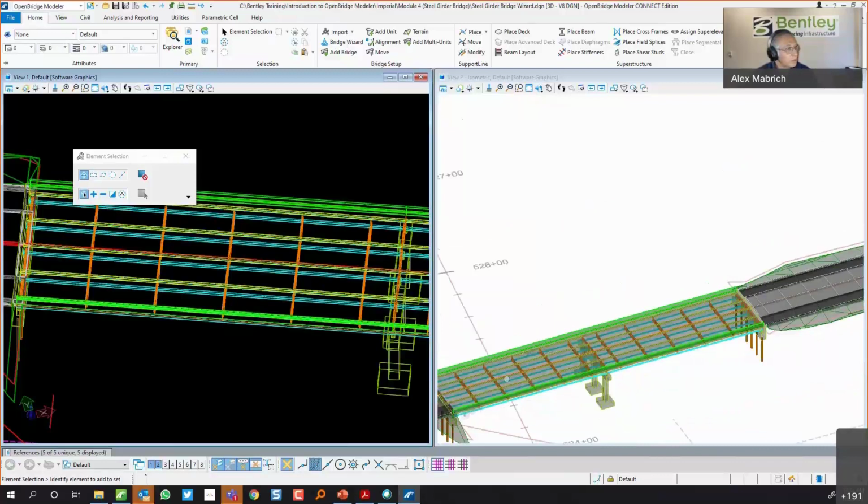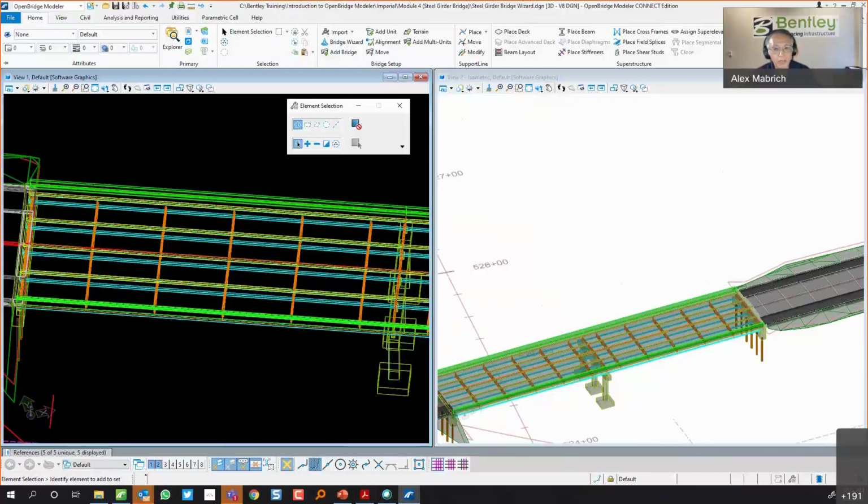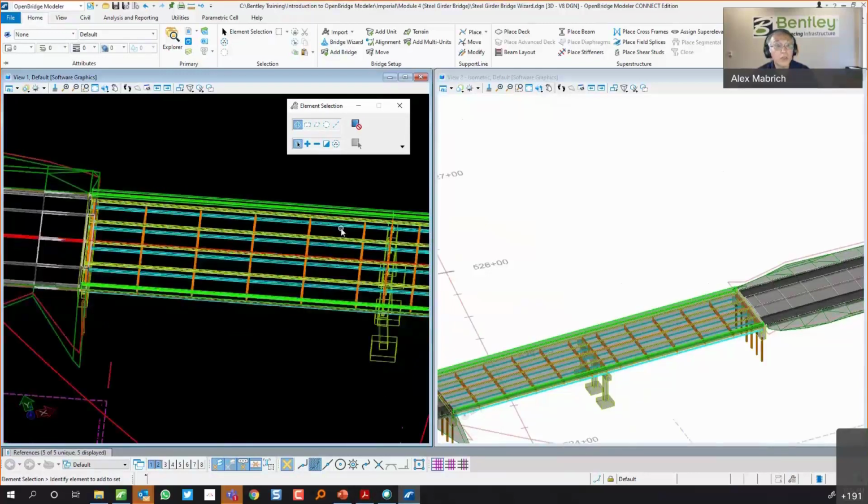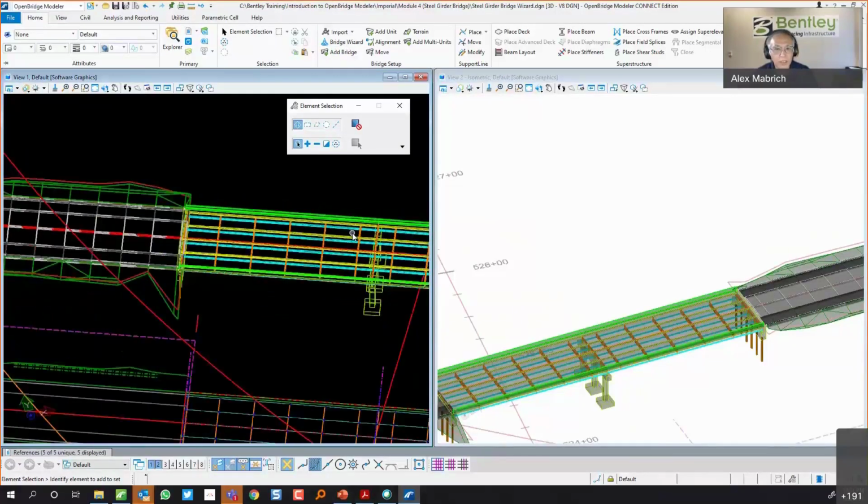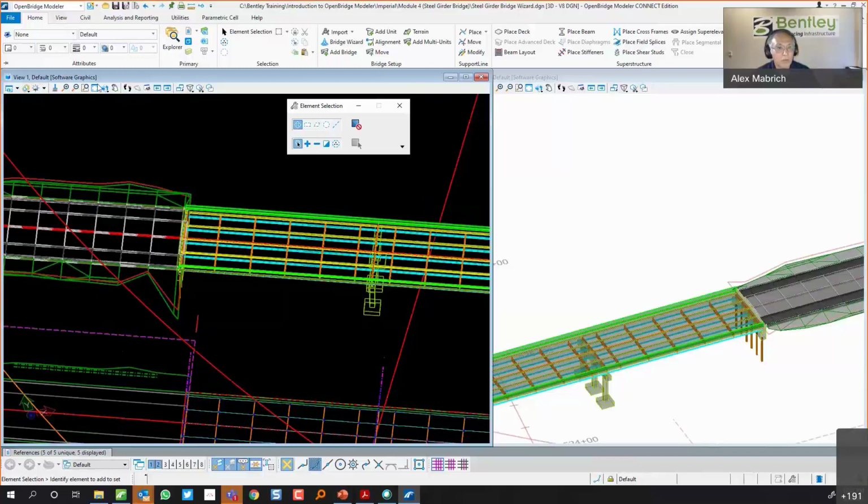So now you can add more options, of course. The manual asks on page 84 to add shear studs. Yes, you can add it, but it will be so many elements that I would rather do these at the end, because as it creates that many elements, it takes a little time to update every single element that is placed. So I would rather do that at the very end of the process. It doesn't make that much difference when you do it, but if I'm still going to be changing things, I'll wait until the end.